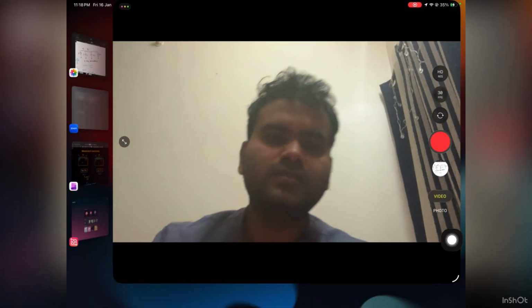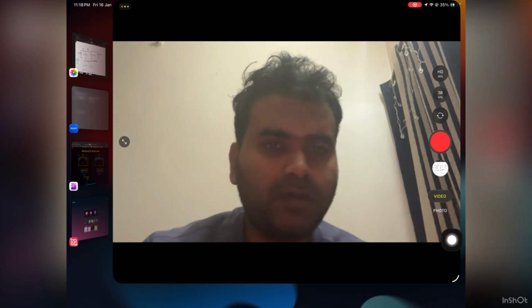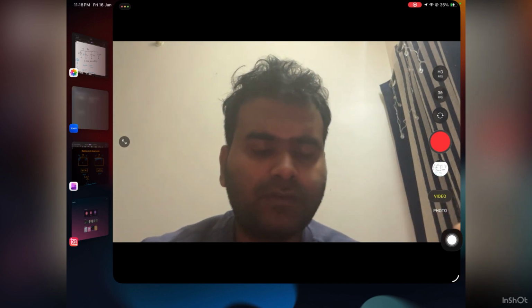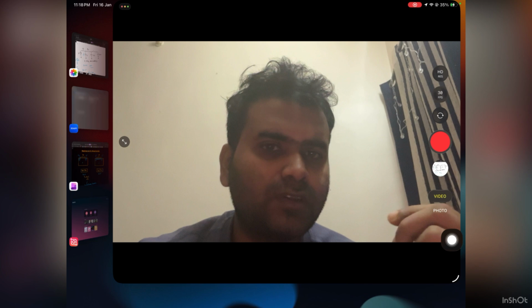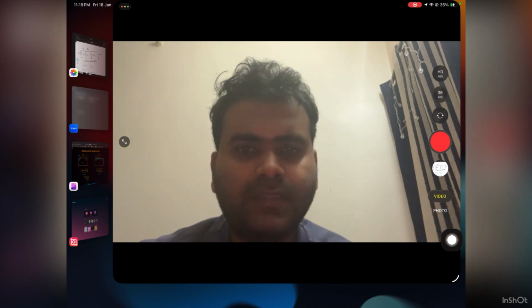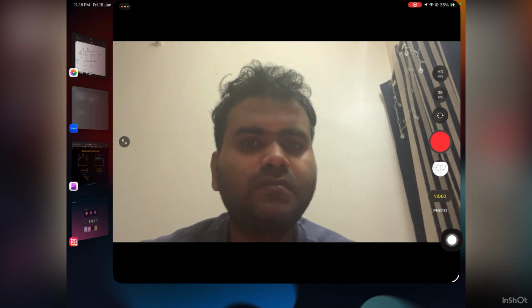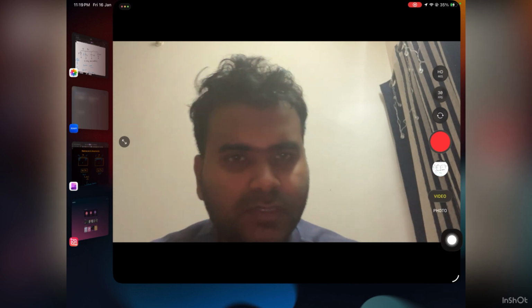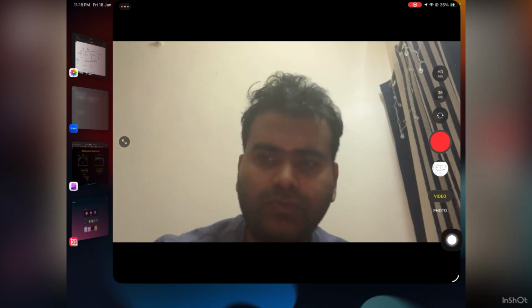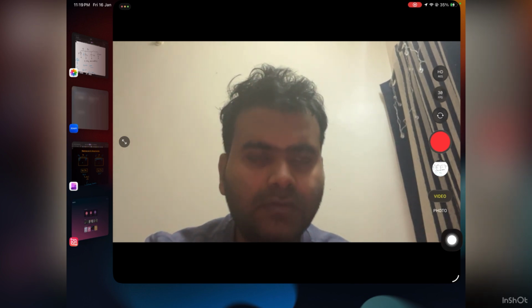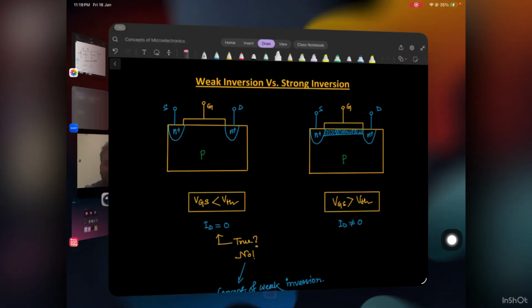So for any analog circuit, we mostly consider three regions of transistors: the cutoff region, the linear region, and the saturation region. We also assume that in the cutoff region the drain current is zero, but that is actually not true. So in today's video we will see a concept called weak inversion.